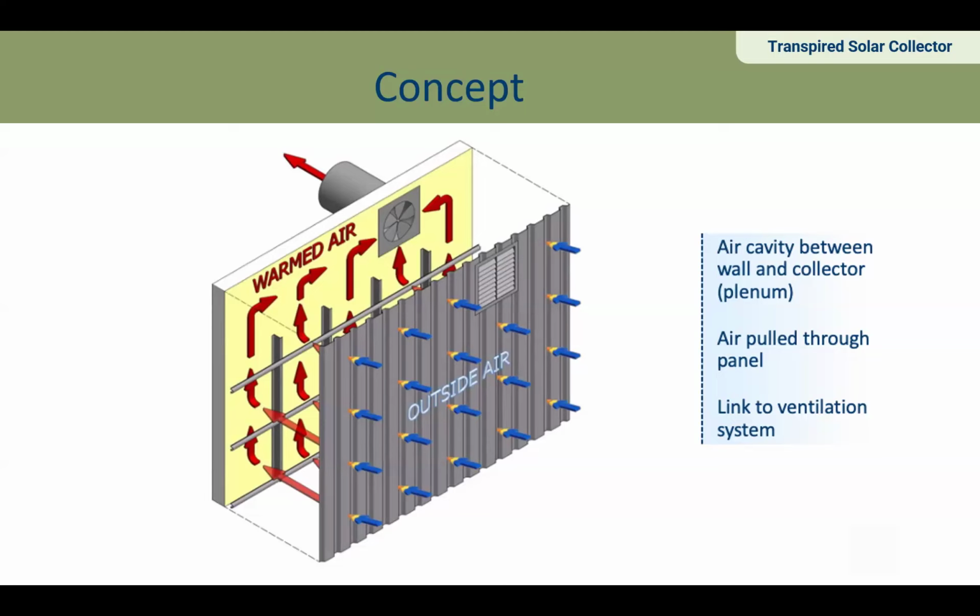Now, the one caveat you'll see here in this diagram, there is a louver there. It doesn't have to look exactly like that. It doesn't have to be as prominently placed, but we did this intentionally because you do have to have a summer bypass louver. When your building shifts into cooling mode, last thing you want to do is be pulling in 150 degree air instead of 100 degree air. So that's what that is about on that facade schematic here.